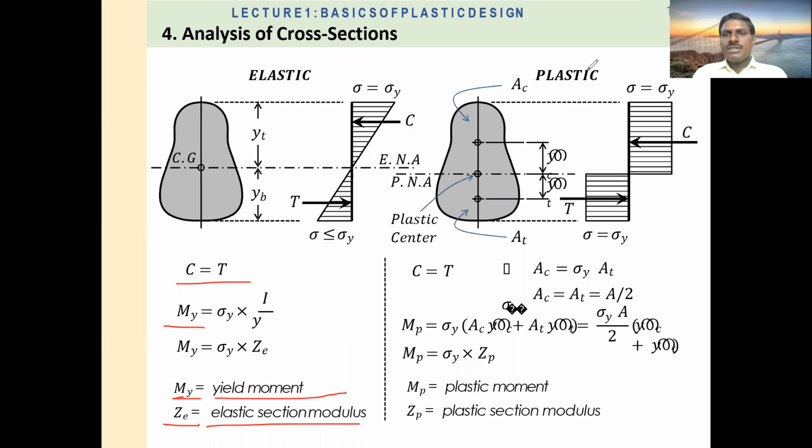Now again, in the plastic condition, compressive force is equal to tensile force. So this compressive force, the area in compression, is equal to sigma y into A. Area in compression means stress at yield into area in tension is equal to stress at yield into area in compression.